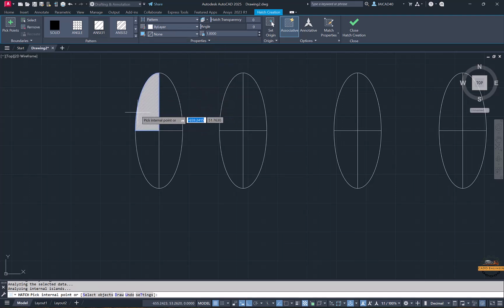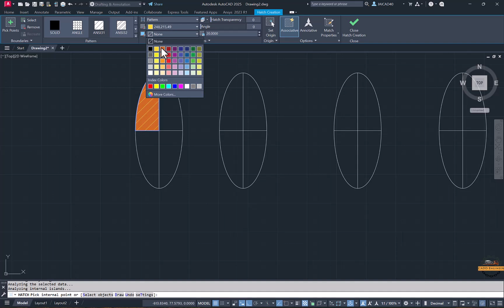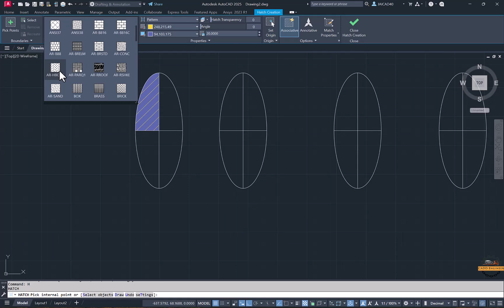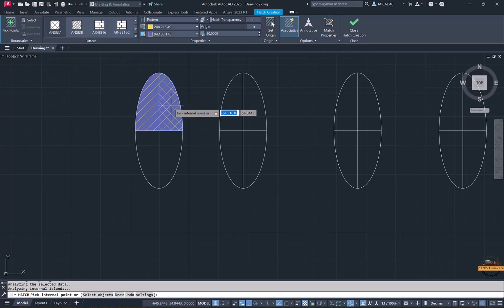When we fill the hatching, sometimes it is not visible clearly. What you can do is put some scale value here, like if it's 50, I put it here, or we can just change this to 20. If you want to add colors also, you can do that. If you want to fill some color inside that part, you can do that also. Okay, we can choose some color like this. Here we have a variety of shades available. We can use different types of shades and textures; we can take from here and apply. If we don't need these colors, we can change them to the colors we require. So like this we can put hatching.